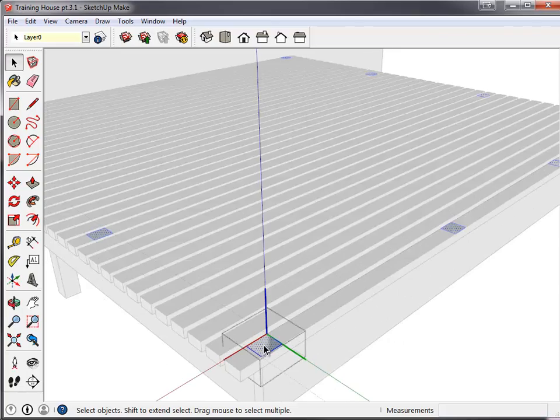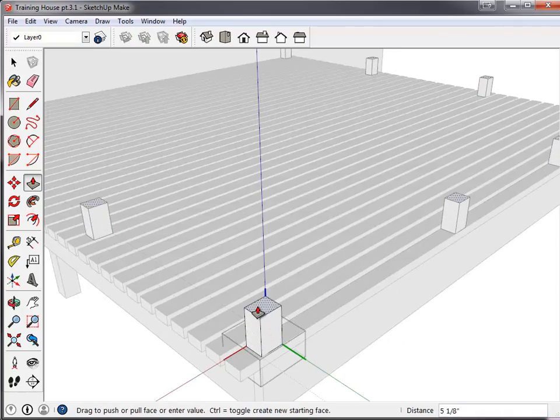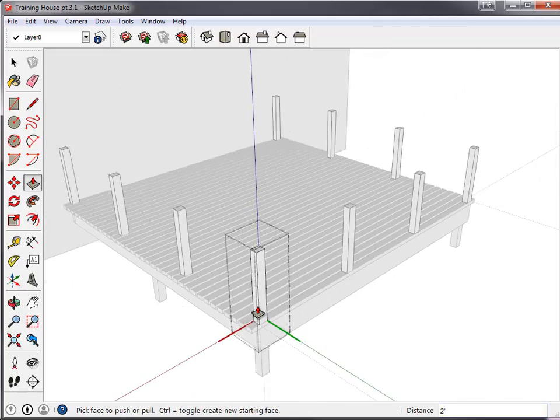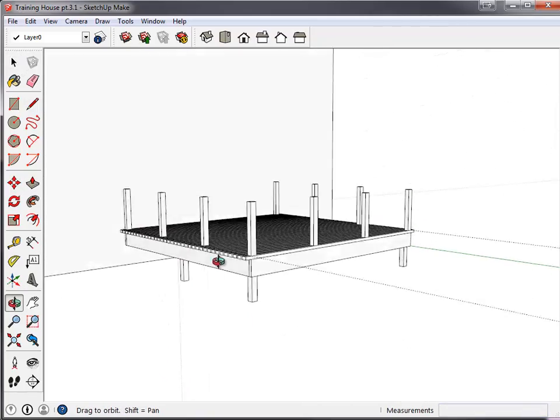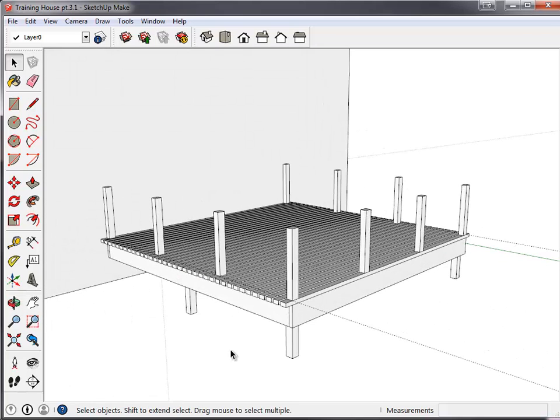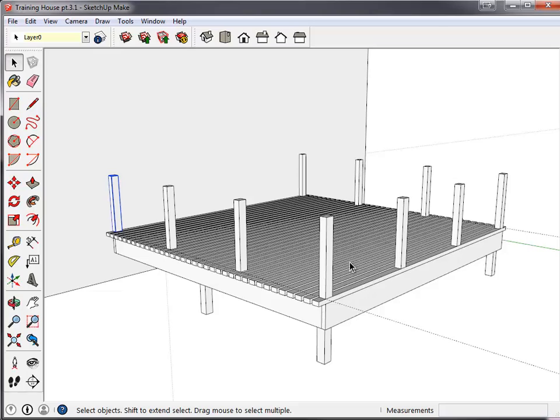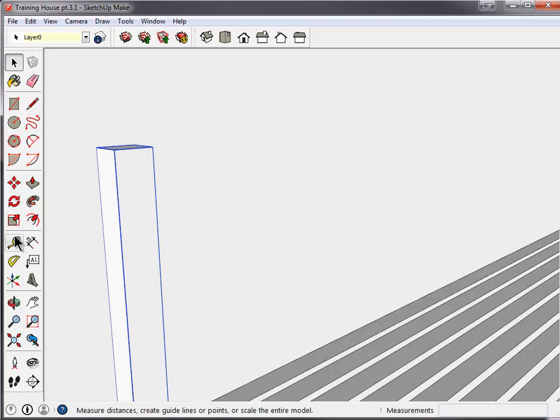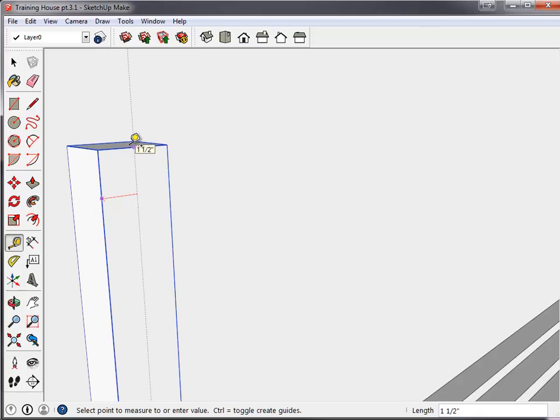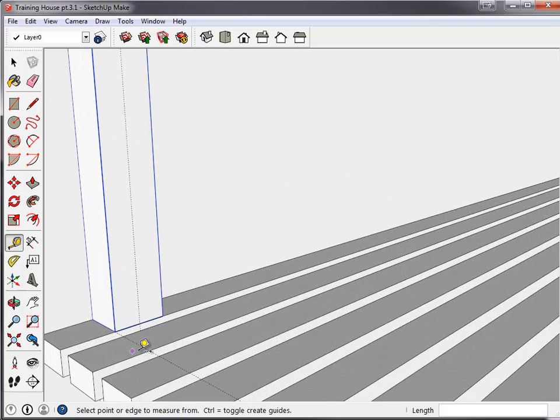Did this correctly, we can double click our component, use our push pull tool for 2 feet up. You should now have all your posts push pulled up to this position. Moving over to the back post, we will create the railings that run along and through each of the support poles we just made. Zooming in, we'll need 3 grid lines, 1 to the middle, snapping your midpoint, 1 down 3 inches from the top line, and 1 up from the top line.